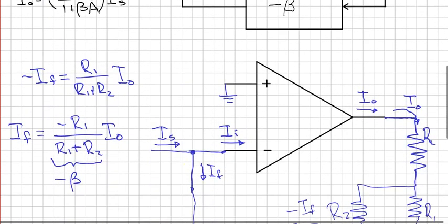Notice these input things are in parallel here. In other words, the source right here, which comes in, putting in I_S, is in parallel with the input current and the feedback current there. So that's how you do parallel current feedback to make a negative feedback on an operational amplifier.